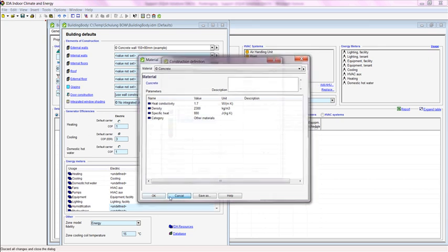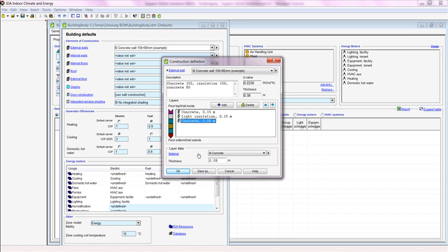We now want to add an additional material layer into the construction. First we select the location where we want to add the layer, and then we click on the Add button. We then also need to attribute a material with this new layer. What we have so far available is all the materials which have been copied across with the constructions which we've attributed in the first place.